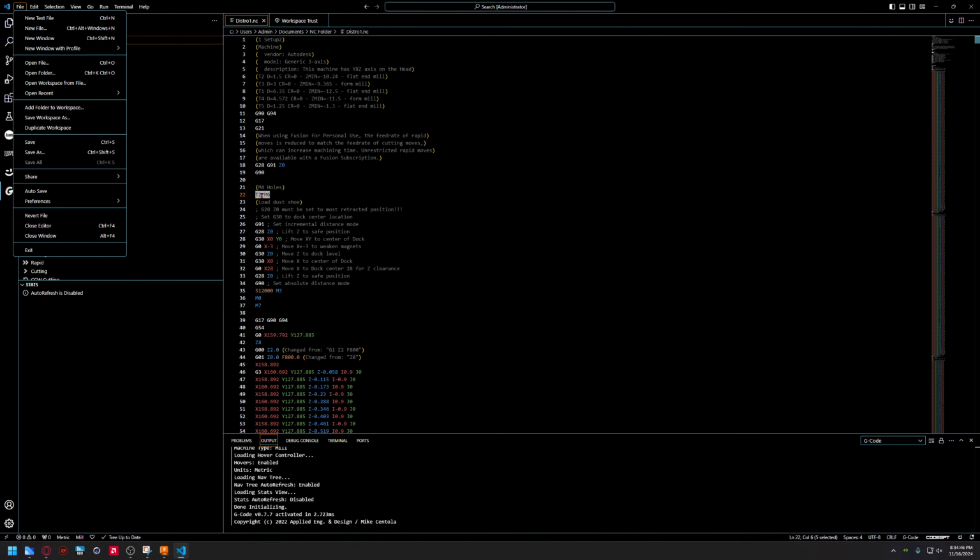First it does the tool change, then it loads the dust shoe, which is this section in here, and turns the spindle on. It pauses so I can make sure everything's correct. Even though I do the tool changes, I usually add the pause in there just in case the tool moves in the ATC collet or something, God forbid, so it allows me to catch it. And the M7 is the command for the vacuum system to be turned on. So that's what I use for the vacuum system.